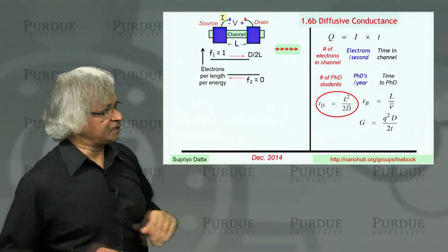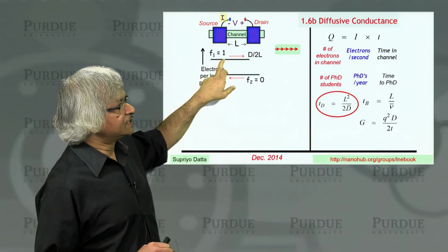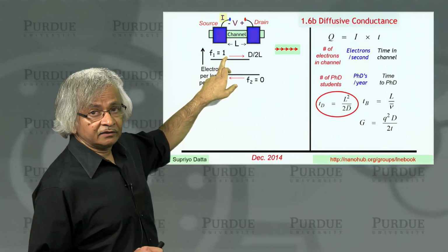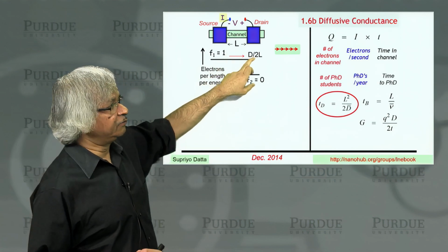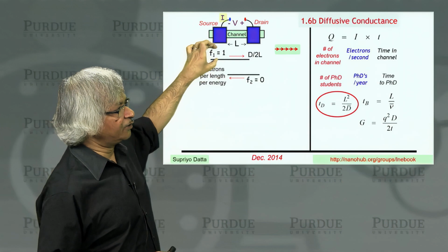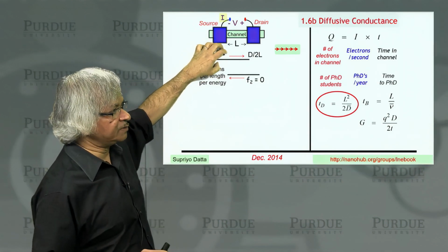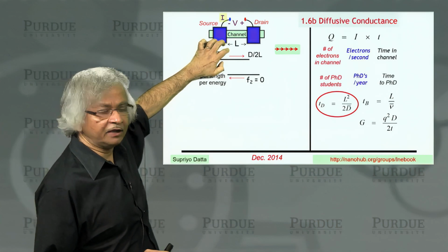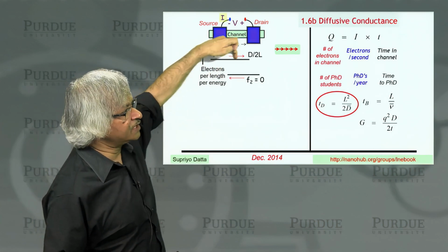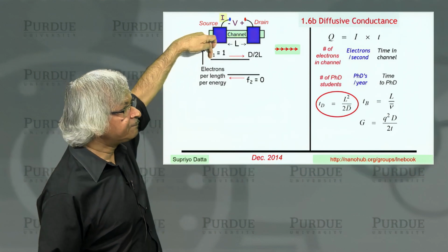For ballistic transport, we can say that all the states that are carrying current from source to drain will all be occupied if let's say the Fermi function in this contact at this energy happens to be 1, which means if all the states here are filled, then all the states in the channel will also be filled because they're all coming from here.